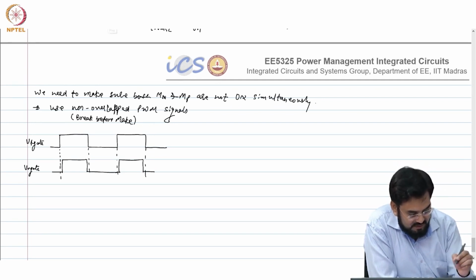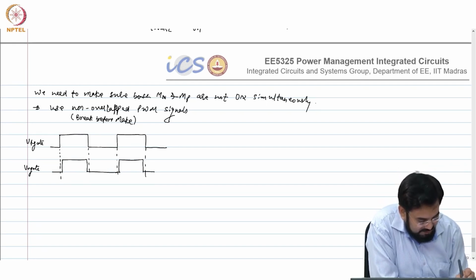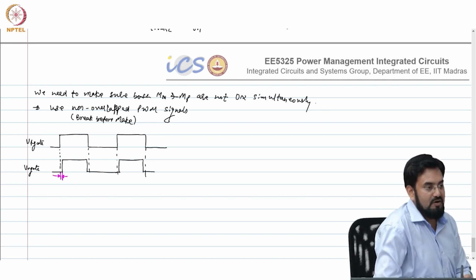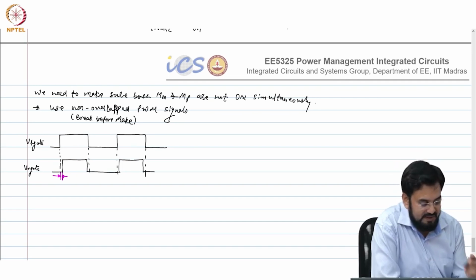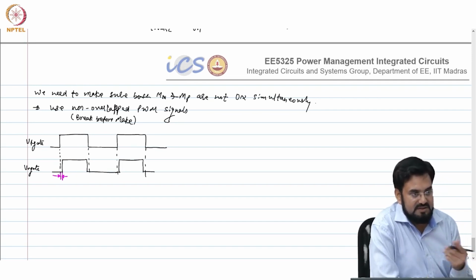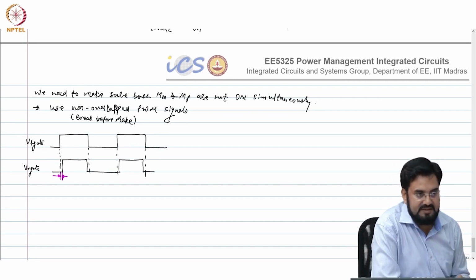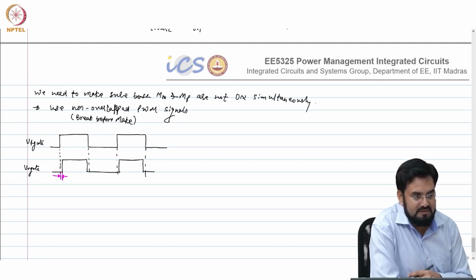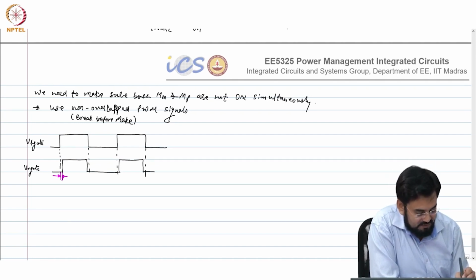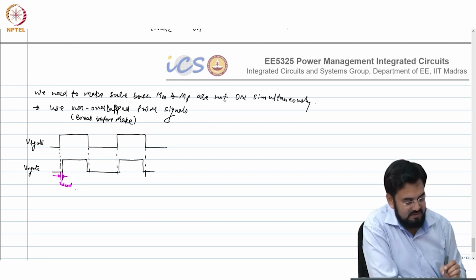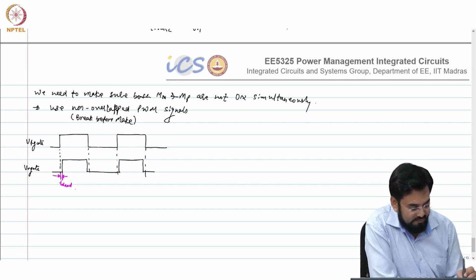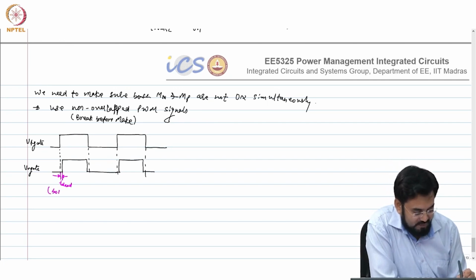So this is the time actually where both FETs are off. So your P gate is high, so that's a PMOS, so that is off, and N gate is low, so both FETs are off, and this is called TD, or I'll call it T dead. Both off.